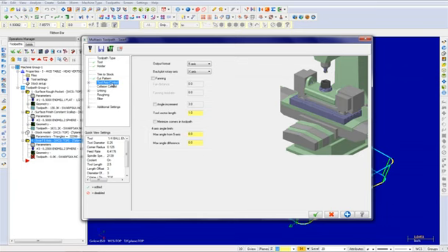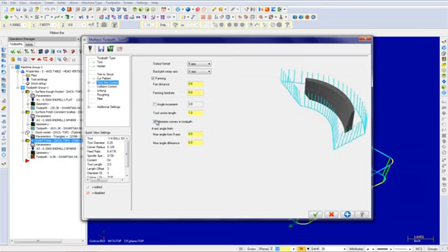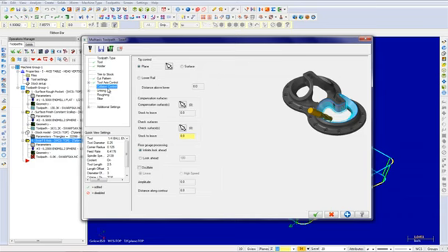Select Tool Axis Control. Enable Fanning. Change the fan distance to 0.5. Fanning creates vectors that are not perpendicular to the upper and lower rails. Angle increment is an angular measurement between adjacent tool vectors. An additional vector will be added to the toolpath when the angle between calculated vectors is greater than the angle increment value. Minimize corners in toolpath removes the vectors immediately before and after any corner in the toolpath. Enable this. Select Collision Control.